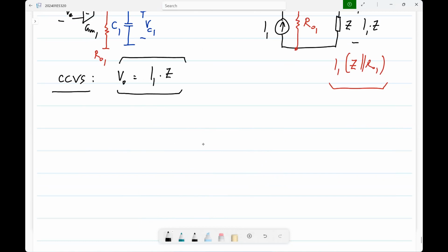What will that do? But that's not a V. Here we want a current controlled voltage source. What is a good way of getting any relationship? Yeah, I mean, by now you should know. I know only a couple of things. Negative feedback is one of them. So answers to half the questions can be negative feedback. Okay. So we can use negative feedback to realize this current controlled voltage source.